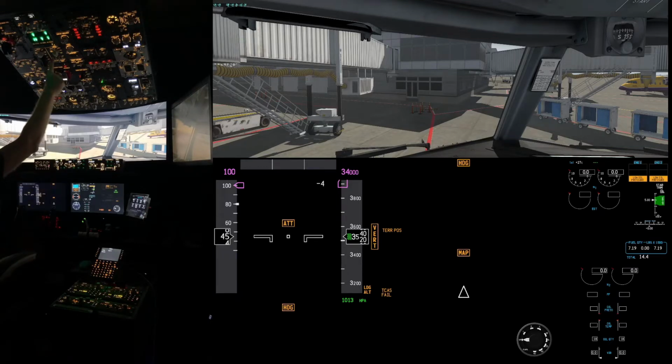Then we come down to cabin utility, turn that on. IFE passenger seat, we turn that on. That's AC power powering those systems. Coming down here, there's nothing we need to do here at this point, so we've got equipment cooling in the normal position. The emergency exit lights, we're actually going to arm those, and we're going to turn on the no smoking sign. We're going to leave fuel because we haven't actually fueled for our trip yet until we put that fasten seat belt sign on once we've finished refueling.